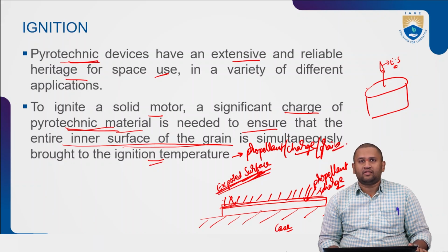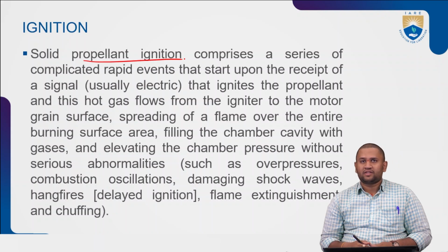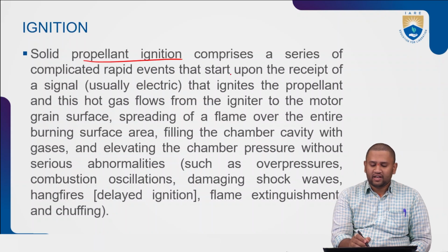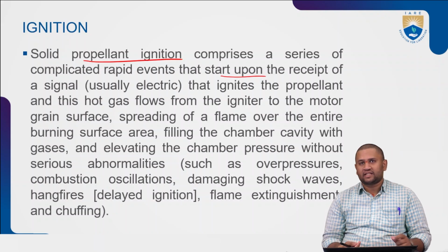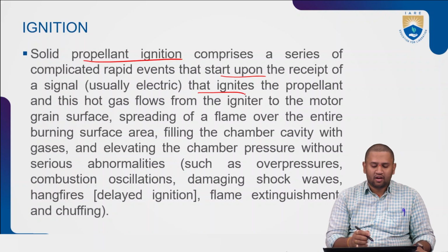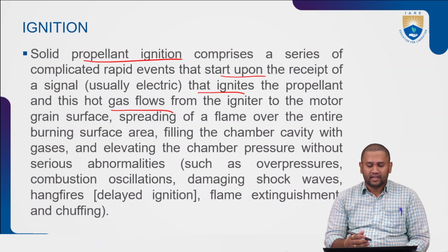Now, continuing the same, solid propellant ignition comprises a series of complicated as well as rapid events that are required to start upon receipt of a signal, particularly an electric signal, that ignites the propellant, as the hot gas flows from the igniter to the motor grain surface.